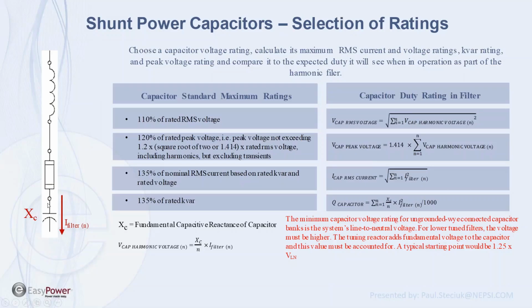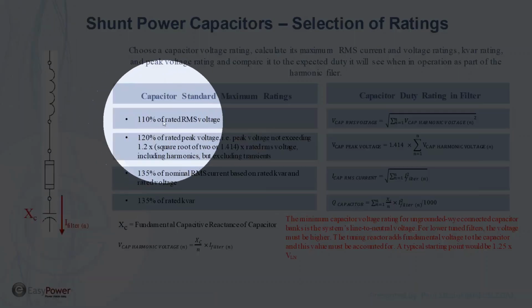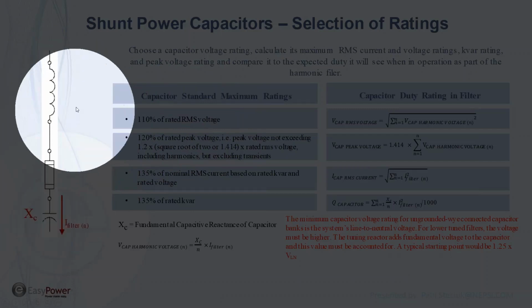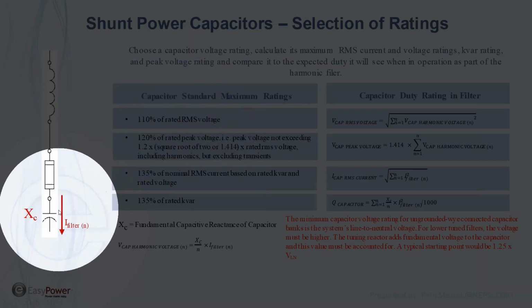So this is what you're basically comparing to. You're doing 4 points of evaluation. You're saying, well, what is my RMS voltage? Well, we can calculate 60 hertz voltage very easily here, and you have to calculate your harmonic voltage also.